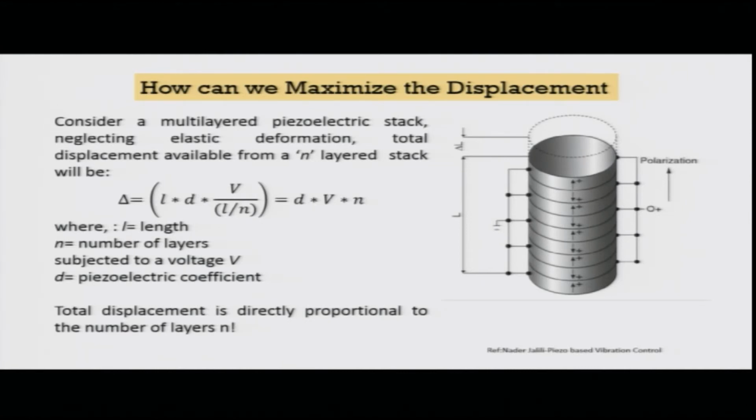Well, how about if I go in terms of multi-layering of this piezoelectric material. So, suppose I have actually chopped, as you have seen that particular piezoelectric fuel injector have given us some clue that they have used blocks of such things. So, suppose I make such small discs and make n number of such discs. In that case, what will be the displacement that will be available from the system? Well, each one of them individually, if that same voltage is what I am using, then it is not over the whole thickness, but over that thickness divided by n. So, that electric field intensity increases n times.